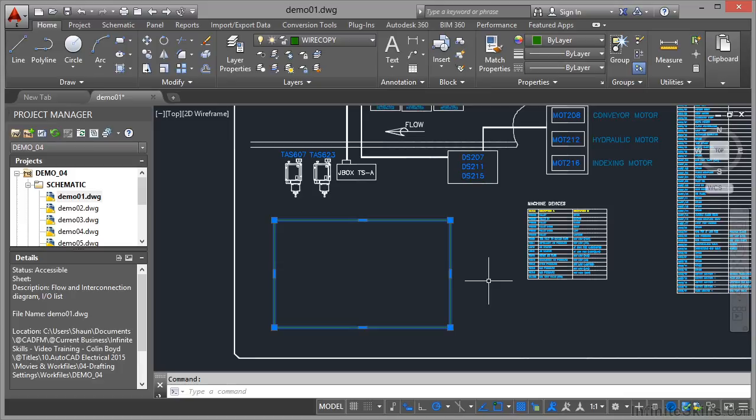Now, this does happen quite a lot in AutoCAD, AutoCAD Electrical, any other Autodesk product, where you're relying on geometry and drafting. Sometimes people draw things over the top of something else to use it as a reference, and you sometimes forget to delete the reference object. So in this case, the white one might have been the reference object. What I've done is I've used selection cycling to delete the reference object and leave the object I want in place. That's how selection cycling works in AutoCAD, AutoCAD Electrical, and also all the other flavors of AutoCAD, whichever one you're using.